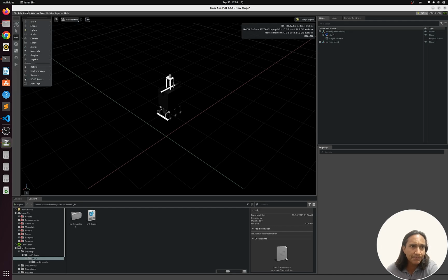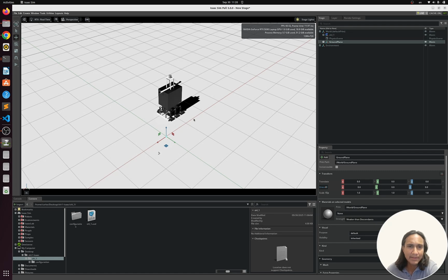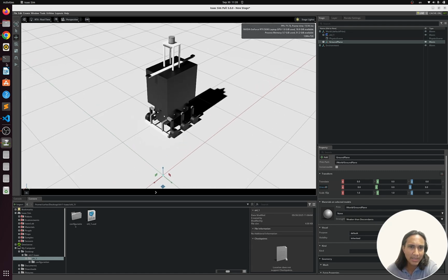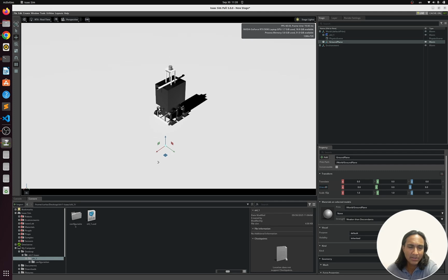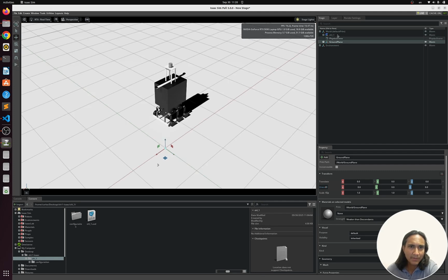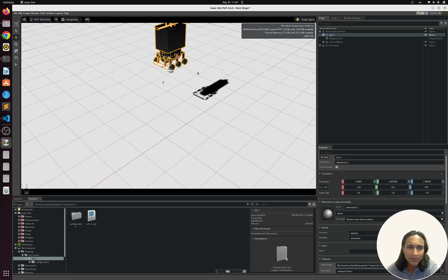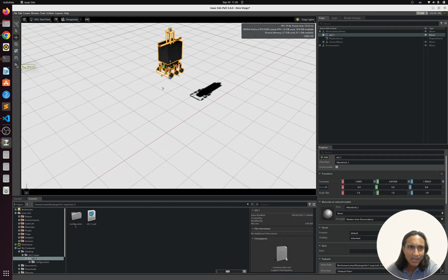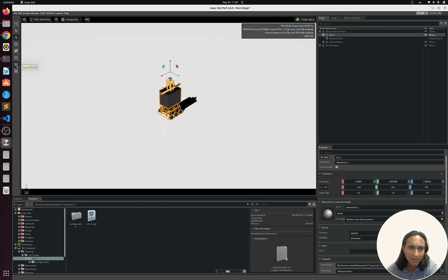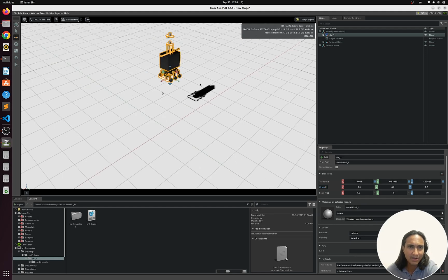Let's go to Create, Physics, and then create a ground plane. Now there's a white ground plane there, pretty basic. If we run the simulation, now SHL1 doesn't fall. To make it more obvious, I'm going to select SHL1, make sure to select the Move tool, and drag it up by dragging from this blue arrow. So now it's floating, but when I run the simulation, it falls from where I set it up.